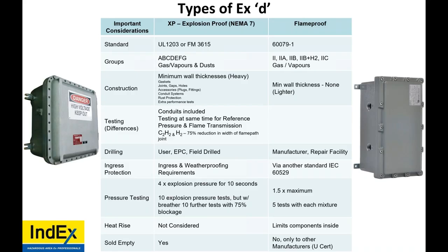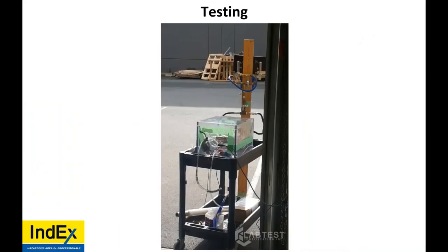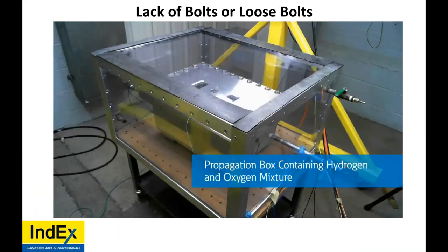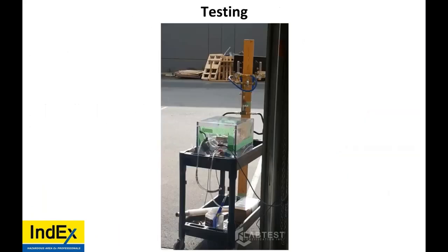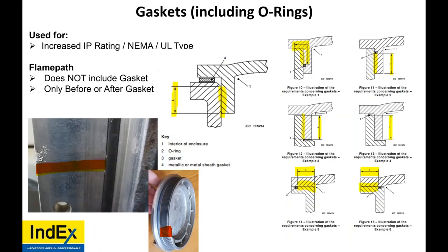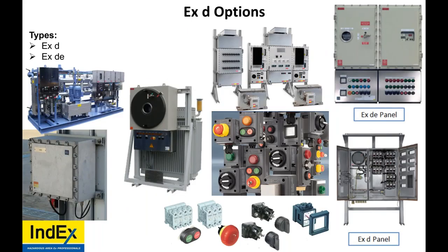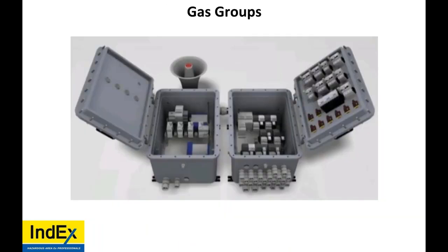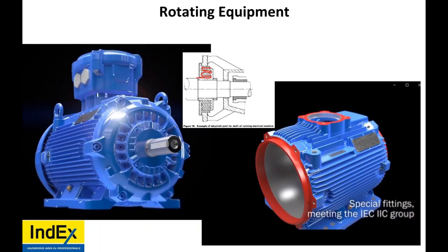In EXD, what? Okay, so sometimes you have an EXD motor, which is so big that you need to purge the gas out of the enclosure before you start up the motor. So there are hybrid motors that are EXP and EXD. So part of their purge operation, before startup, they purge all the gas out as to not cause an explosion. So Zone 2 is equivalent to Div 2.